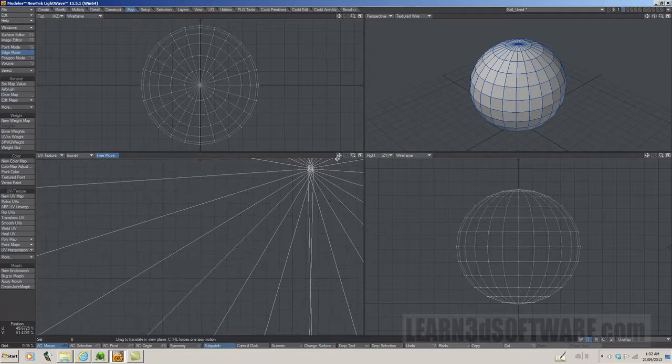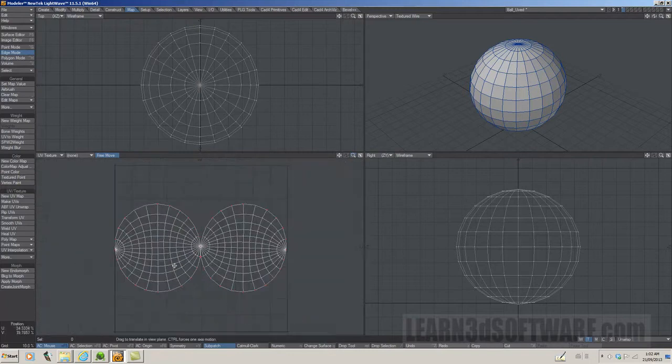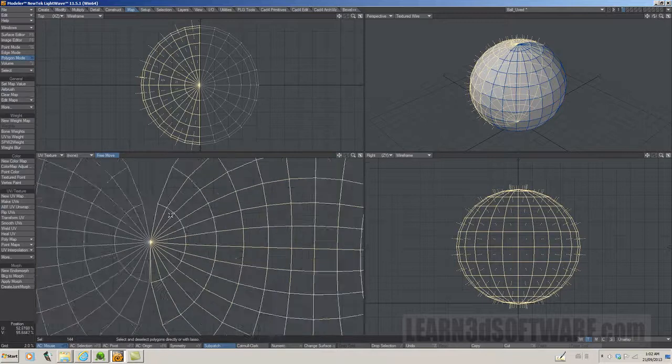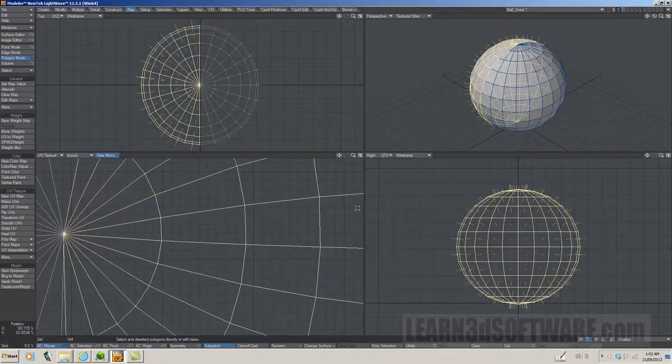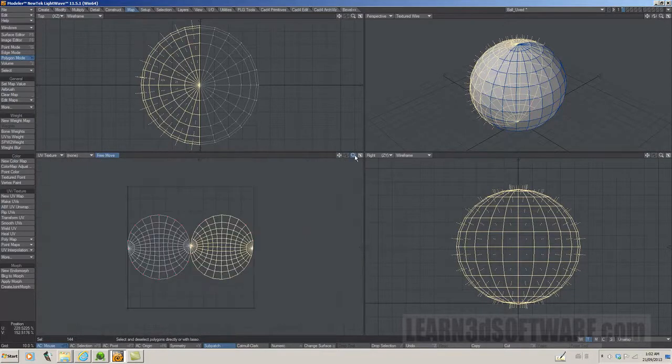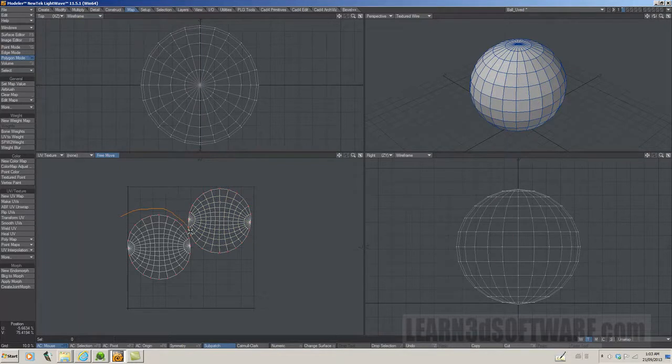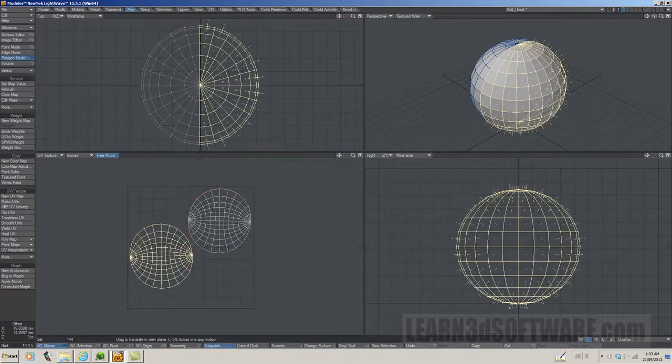We zoom in so we can see a little bit of overlapping. So all we need to do in that particular case, let's just come in like so, and let me make sure that we haven't accidentally selected anything that shouldn't be selected. Let's go T for move. We're in free move mode, so that allows us to move the UV islands around.